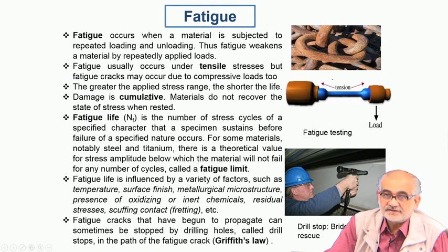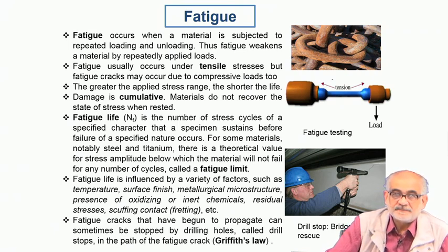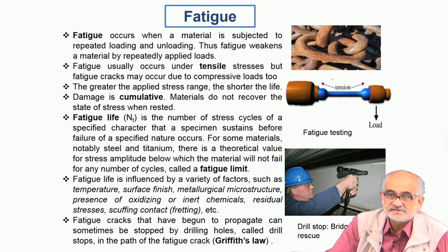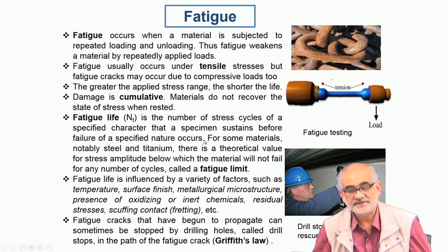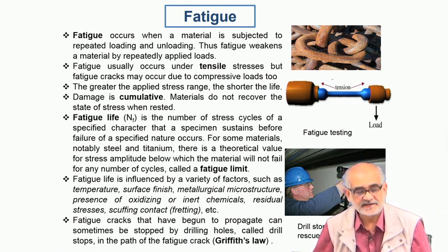So in order to prevent or arrest this, we would like to create solid components which are undergoing repeated cyclic loading or deformation, for example a gear, a rotor, a rotating blade, a turbine or a shaft. In all such cases, we would like to create a situation where the state of stress on the surface is compressive in nature and not tensile, so that even if a crack initiates, the crack first has to overcome the loading which is towards each other, as is expected in compressive loading, and then go into the tensile regime, and only then can the crack open.